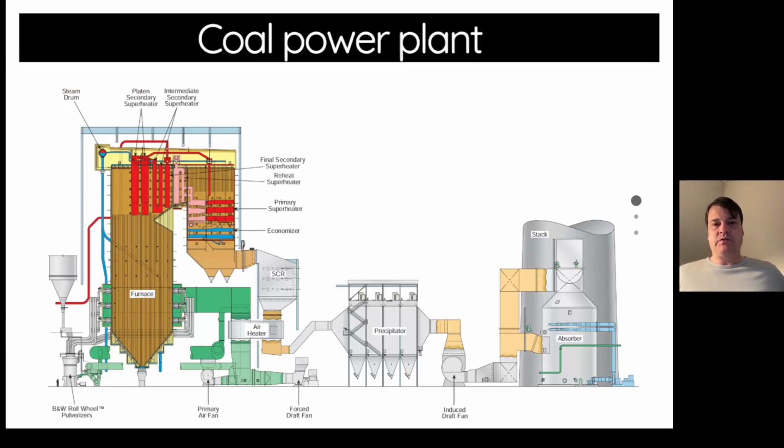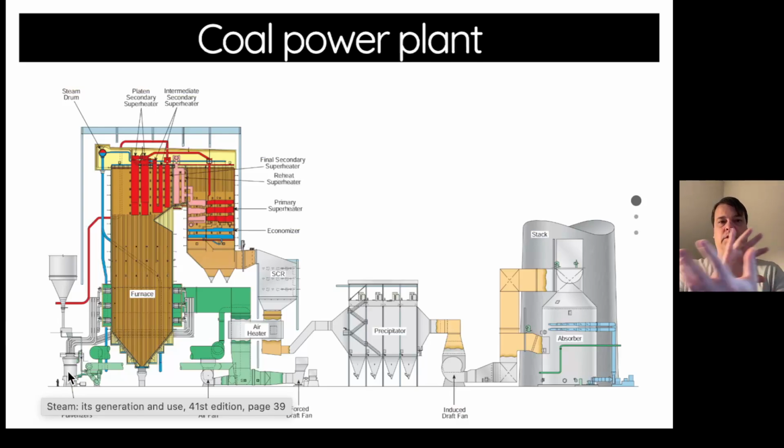You can see here that the coal starts on the left and ends on the right as the combustion process happens. The coal is brought in as a solid that's chunked down to maybe marble size, gravel size pieces. It enters a pulverizer that consists of a race mill with a rotating drum, and the coal is pulverized into a fine powder, maybe 50 microns in size.